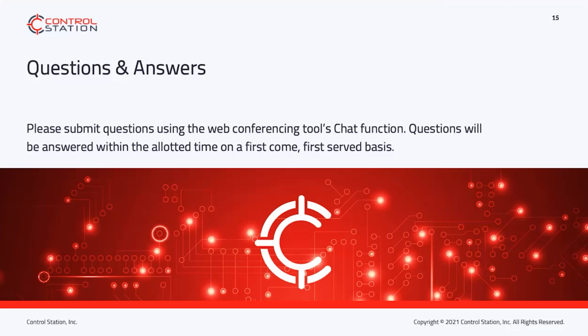Danny, the first question: how does the method that you described apply to level controllers that don't settle? When using this method that I showed, it is generally not necessary to run the experiment for longer than 10 times the effective delay, because at this time, you can approximate it as an integrating process.